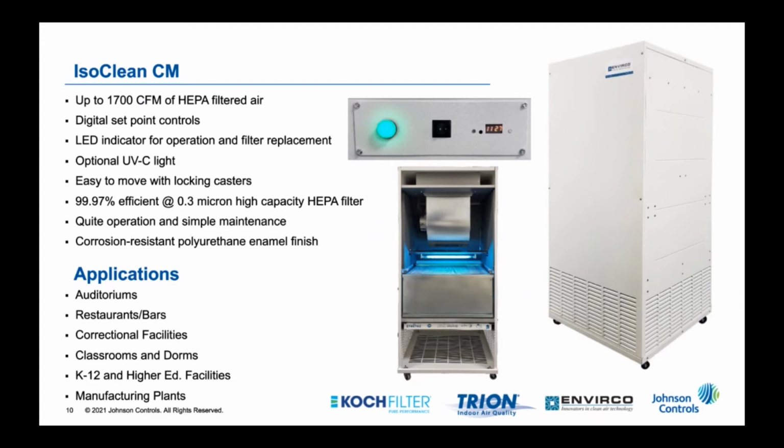If you change that pre-filter and you redeploy the unit and the light stays red, that's an indication that you have a restriction somewhere else in the system, but more often than not, it's going to be the main HEPA filter. So that's how that filter indicator light works. The little display on the right that you see where it says 1127, that's the digital controller that sends commands to the ECM motor.